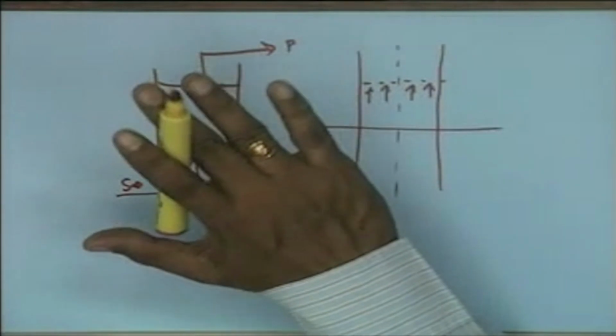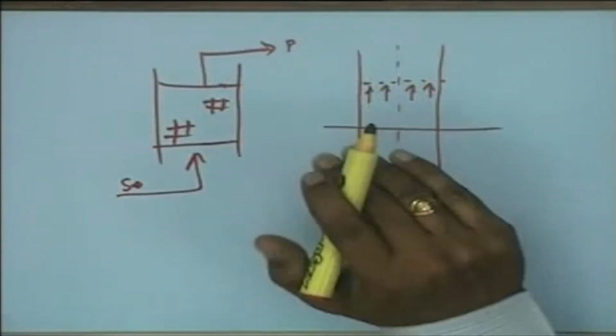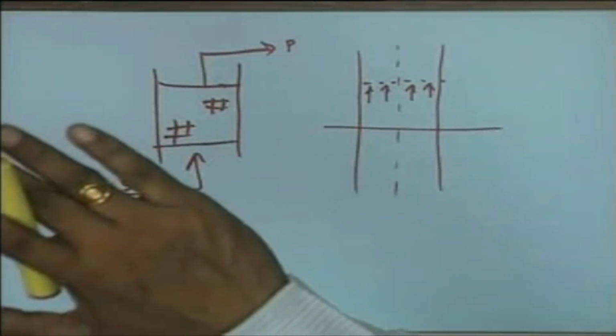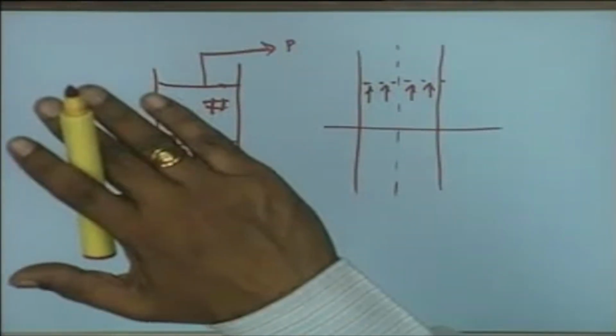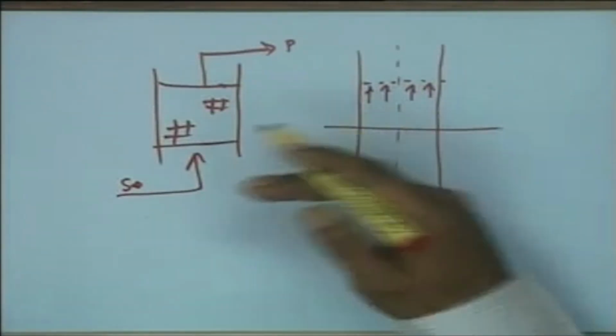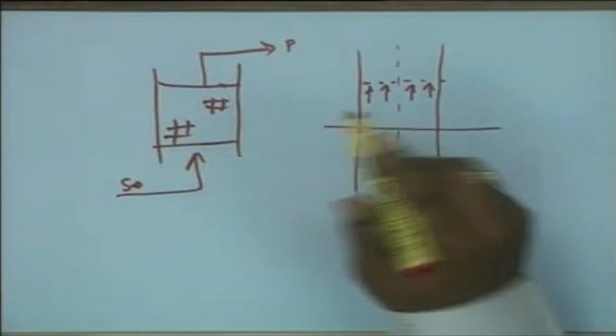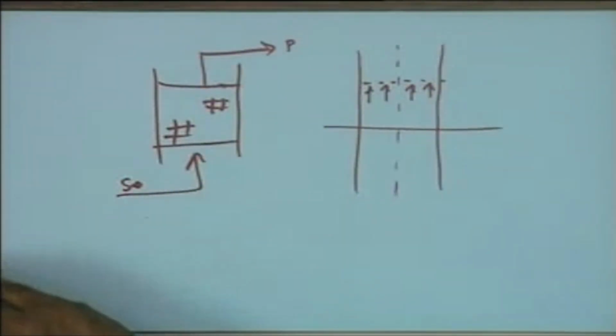That means there are no axial dispersions, and so the velocity profile of the feed stream throughout the length of the reactor is flat. In other words, the feed stream moves almost like a plug, and therefore we call it a plug flow reactor. Broadly, they are essentially packed bed systems, and they can be operated.